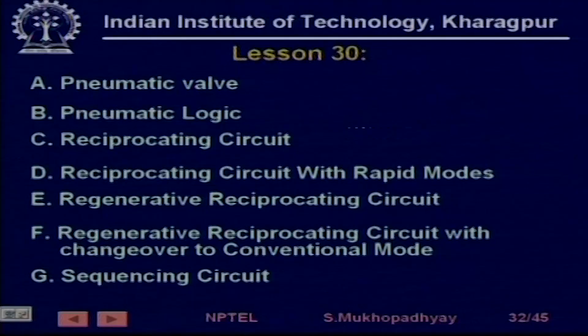and finally we took a look at pneumatic logic, various kinds of reciprocating, and then various kinds of typical pneumatic circuits like reciprocating circuits with rapid retracts, reciprocating circuits with regeneration, so that the pressure energy is not wasted, and then various kinds of sequencing circuits.